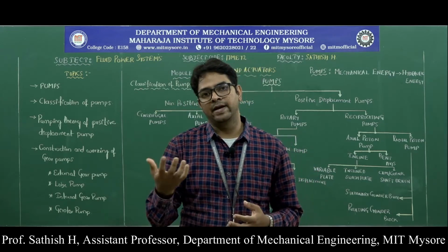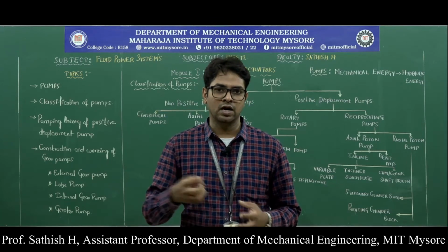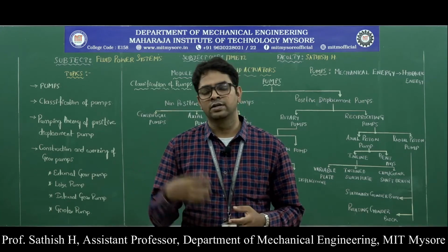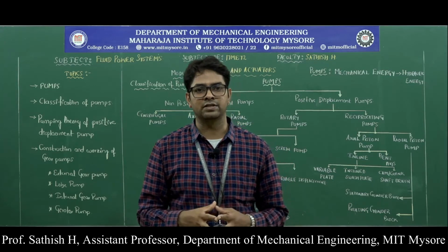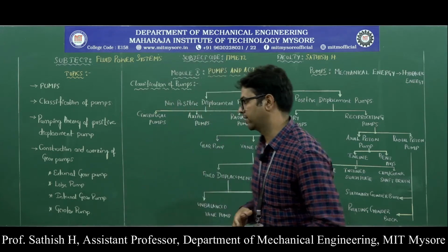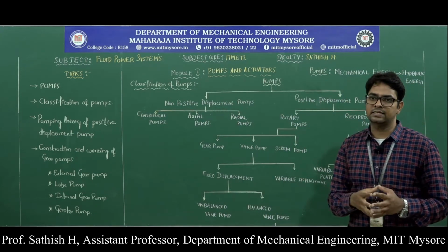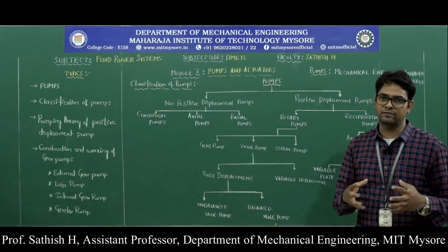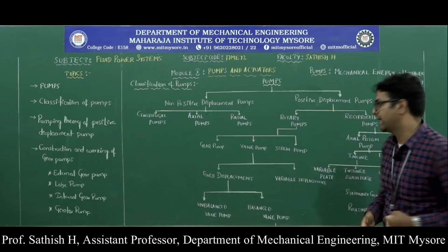The fluid taken from the tank into the cylinder is then pushed out at higher pressure with the help of mechanical action. Reciprocating means the piston is reciprocating inside the cylinder, which creates a pumping action that converts mechanical energy into hydraulic energy.